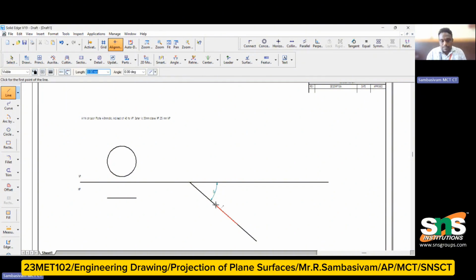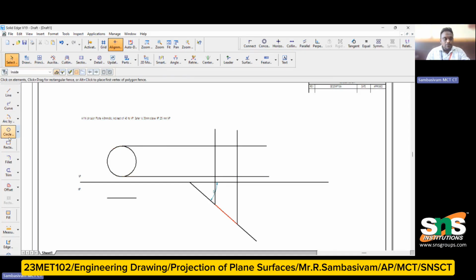Similarly, as I said earlier, I have to draw the perpendicular lines of the trace lines. Similarly, from this point to this point, from this point to this point, from this point to this point. So I'm going to remove this, and then I also have to draw the center line, right? This is the center line. For marking purposes, I am going to use this as the center line.